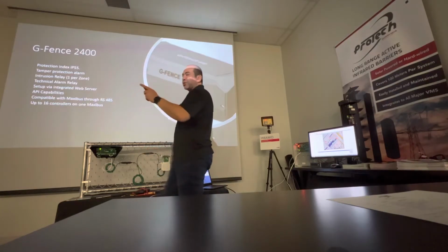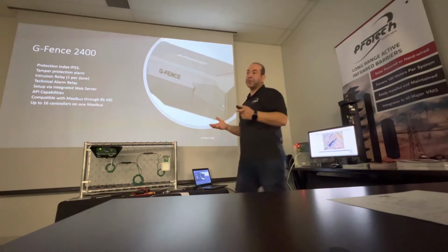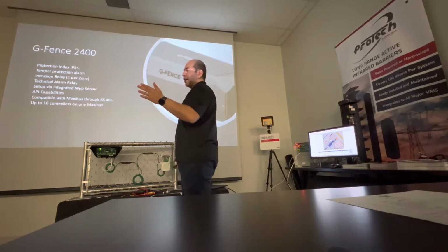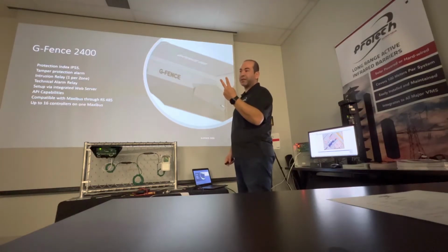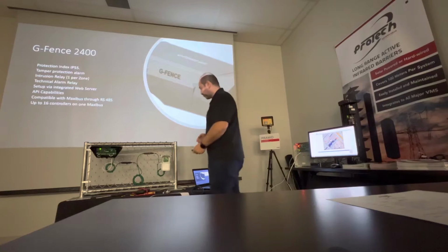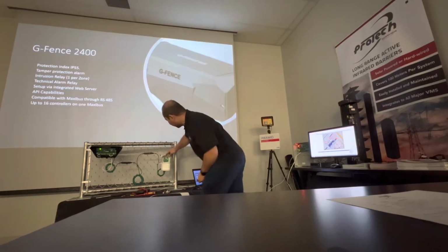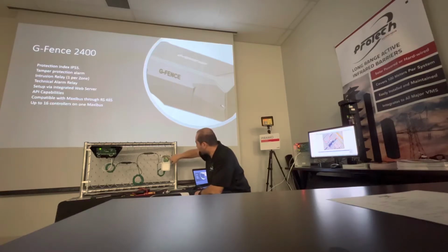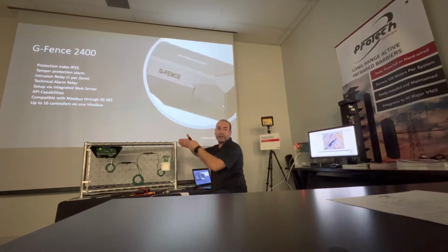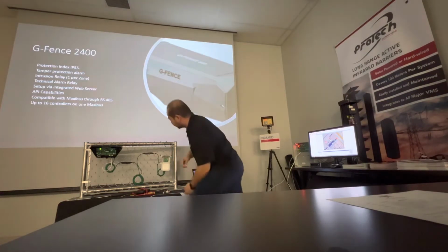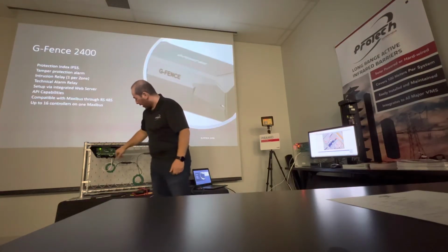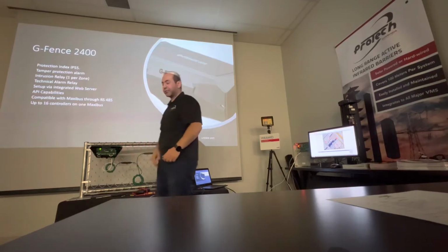But for the GFence 2400, we have the half roll of cable. It's 50 meters, 20 sensors. So let's say that you have like 230 meters total. So you have 2 rolls of cable, 328 feet, plus 1/2 roll of cable. In that case, the same link box has a switch. So it has UT, it means termination link, or you can push to use the link box to tie 200 meters together and to keep going. So it's the same box, it's not 2 independent boxes. So input, output. And it already has surge protection inside here. So it's built in.